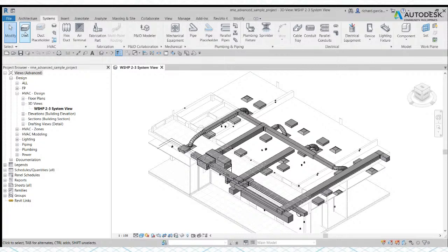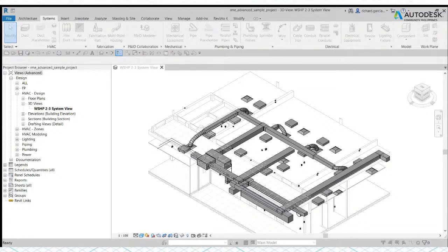There is a way to control this information on your tools every time you hover over it. To do that, go to File again, go to Options, and then I think it's here, User Interface. Then you can see the tooltip assistance. As you can see, it's normal. If you click the drop down arrow, you can put none, or you can put minimal.